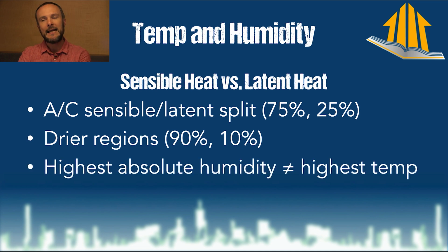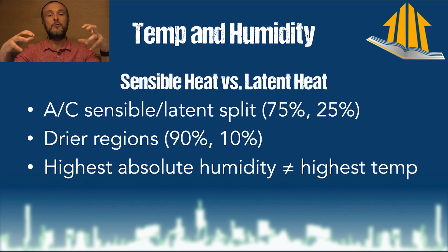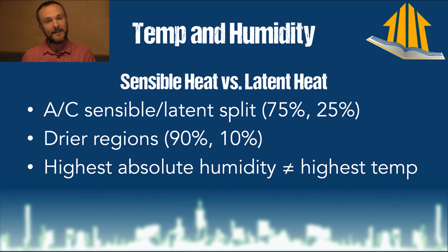So the highest absolute humidity used to be understood to also be the highest temperature. People used to think that if you design an air conditioner for 95 degrees, which is your 99% design day in your area, which I think in Chicago, where I used to be, was 95, then I would also have the highest humidity on that day, and I'd be able to tackle both. What they found when ASHRAE did a study on this is that that was absolutely not true. Actually, the highest absolute temperature, and absolute humidity, when we say relative humidity, what is relative about that humidity is the temperature.